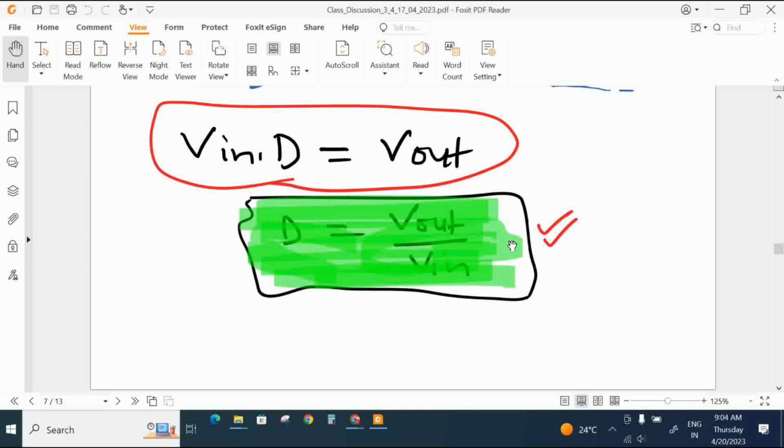Okay, there are again multiple fundamentals on how you calculate your MOSFET. There are multiple important interview questions, like how you can calculate the MOSFET. Then you have to define your VDS, ID, and after that your gate capacitance, RDS on, all these factors should be low. The other thing is that they will ask how you calculate your inductor.